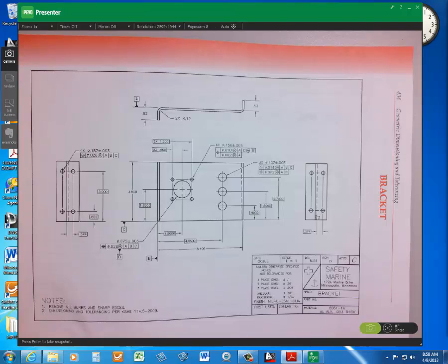The more zeros you see, the higher the precision measurement is expected. And since it's a basic dimension, I know this sounds kind of funny, but it's really perfect. They're theoretically perfect dimensions, and the more decimal places you put on it, the tighter the perfection that is expected.